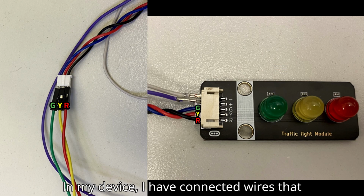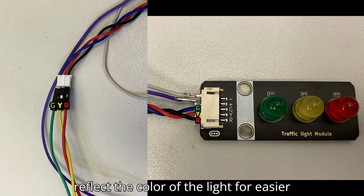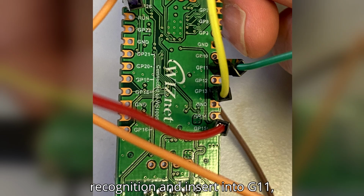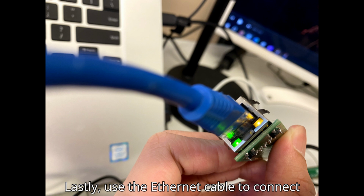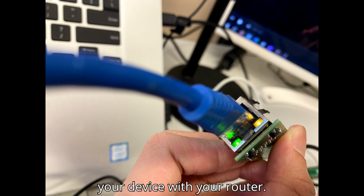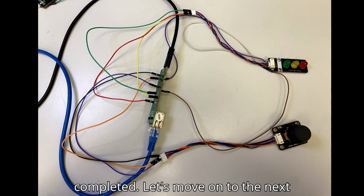In my device, I have connected wires that reflect the color of the light for easier recognition and insert into GP11, 13, and 15 ports for green, yellow, and red light respectively. Lastly, use the Ethernet cable to connect your device with your router. The hardware configuration is now completed.